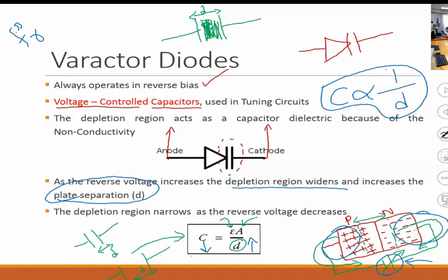So here, the change of capacitance is occurring by simply changing the voltage. That's a convenience. In olden days, with television or radio receivers, when you're tuning a station, and even now, but with the improvements of varactor diodes, it's more convenient from a design perspective.